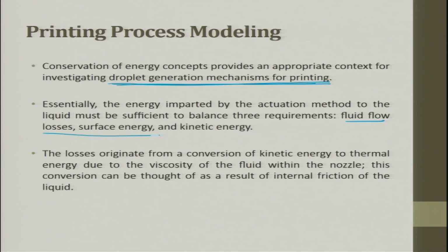Again, this point is very important. The energy balance will be done between fluid flow loss, surface energy and kinetic energy. The losses originate from a conversion of kinetic energy to thermal energy due to the viscosity of the fluid within the nozzle. This conversion can be thought of as a result of internal friction of the liquid.